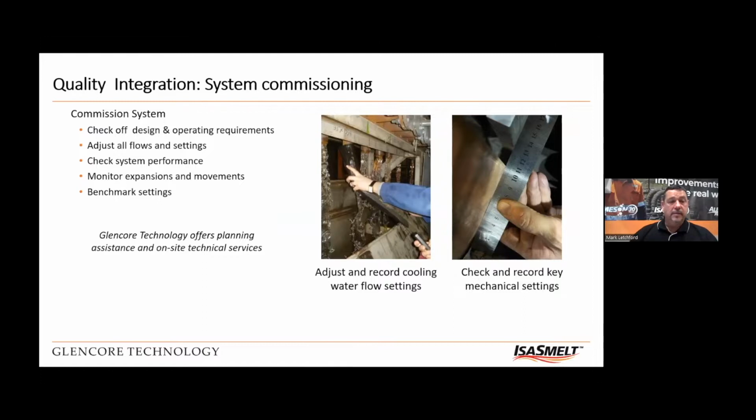In the integration stage, the third step is system commissioning. So that all the process and mechanical parameters need to be checked and set, and most importantly, benchmarked for reference during operation. And again, we always offer to our customers in projects on-site technical services at this stage, and we always find that well-planned commissioning pays off big time in more rapid startups. It's a really critical step.